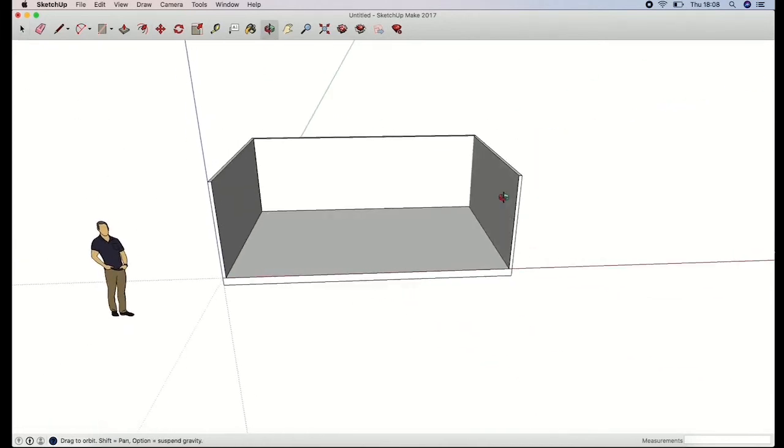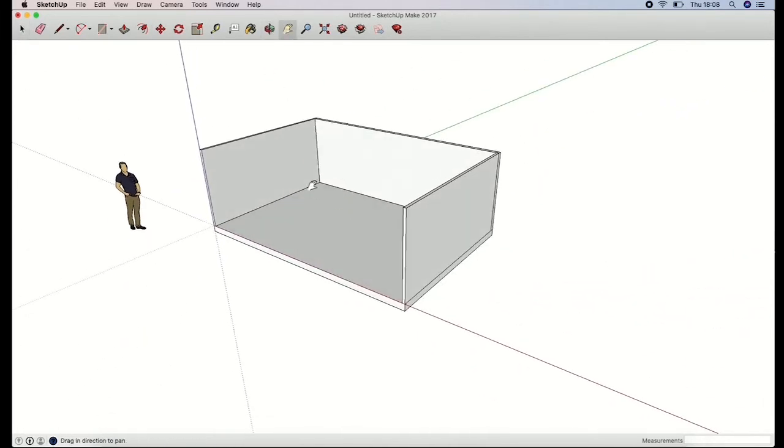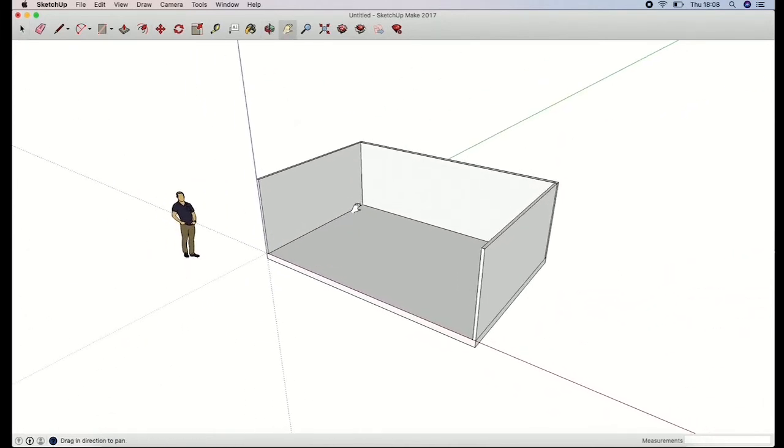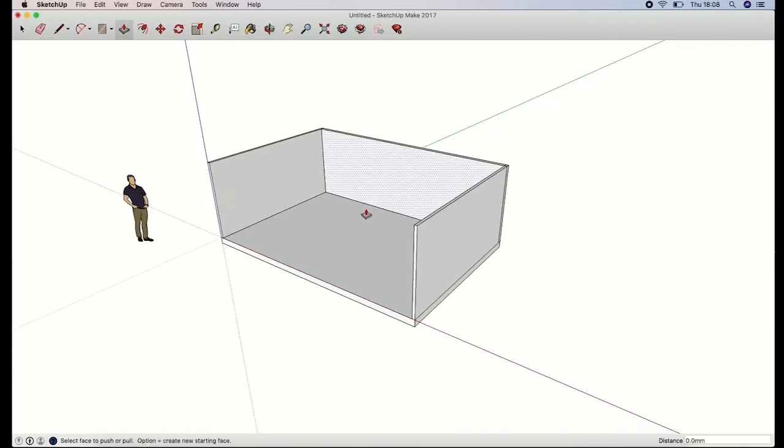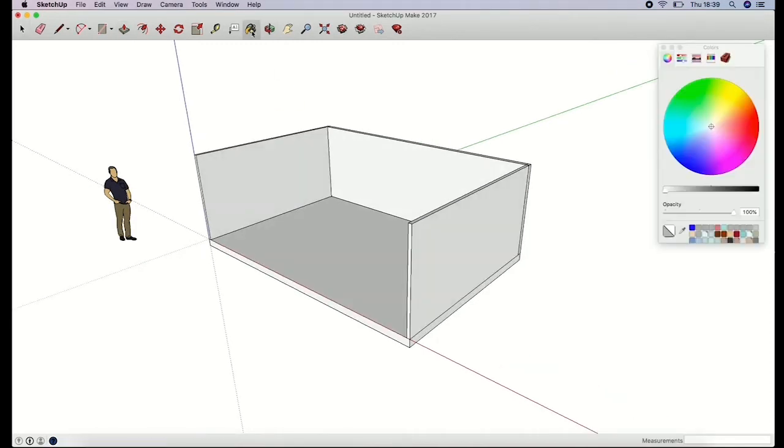If you're creating a space and maybe you want different viewpoints, the other thing you can do is make the wall translucent. Either you could grab the top of it and pull it down so that it's just a kind of partial view. I'm just going to undo that, so Command Z. Or you could, on the paint bucket tool here, bring up the toolbar with lots of different colours. You can select using this wheel here, clicking on this icon and dragging it around, also moving this depending on how light or dark you want it.